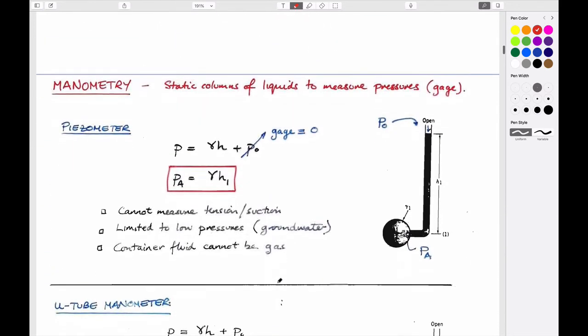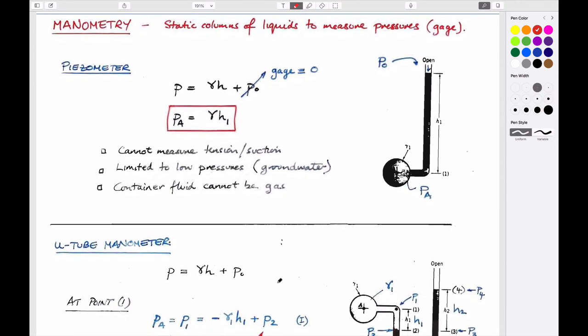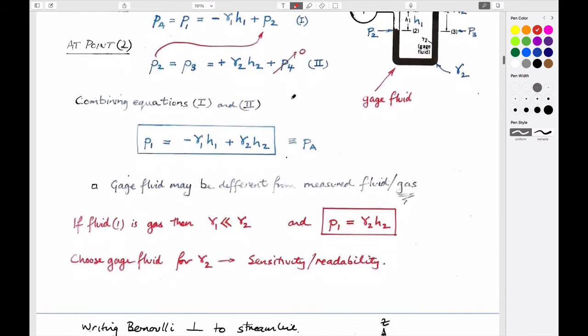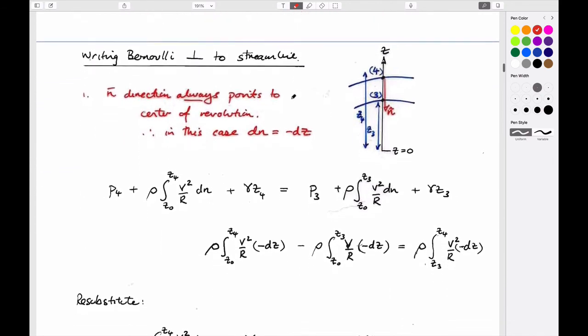So just in terms of summarizing maybe some of the things we've talked about, the manometer equations, we can always get the pressures if we know what the height changes and the unit weights of the fluid by going up or down. We always start from a reference pressure, and from that reference pressure we can calculate the new pressure at a particular point as a function of how high we go up or down, where we use the appropriate manometer rules as well. Like if we go up, we subtract pressures. If we go down, we add pressures, etc. And so we certainly spent some time dealing with that. You should know how to do that.